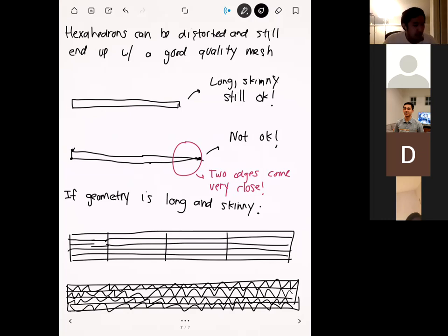Mesh quality is something that you can check as well. I'm actually not too sure how to do it in ANSYS. I'd have to look that up, and maybe we can check that for the next activity. But checking the mesh quality is really important for finite element analysis as well. One of the things they check for mesh quality is aspect ratio. It's not the only thing they check, because there are other things, but it's one of the big indicators that they look at.